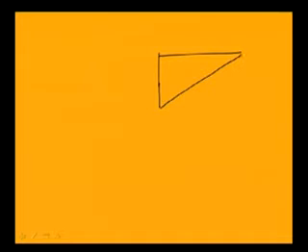For example, let me determine A21. A21 is the displacement at 2 due to a unit force at 1 and forces at other places equal to 0. When a unit force is applied here, the displacement can be obtained from this bending moment diagram, whose length is 3L. As you are applying a unit force here, the bending moment at this position will be 3L. The displacement at this position can be obtained from the moment of this area.